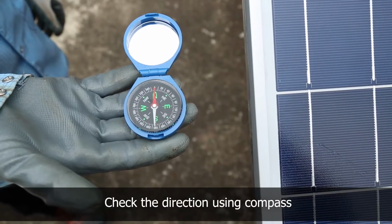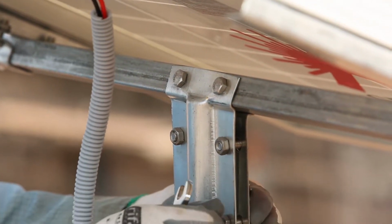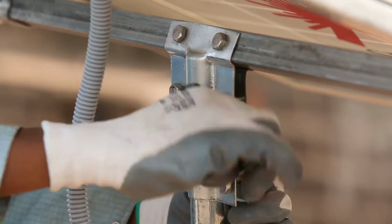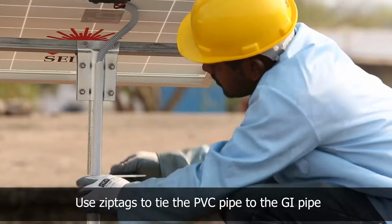Check the direction using a compass and adjust the panel facing towards south direction with appropriate inclination as per the region of maximum radiation. Tighten the module mounting structure using a spanner.